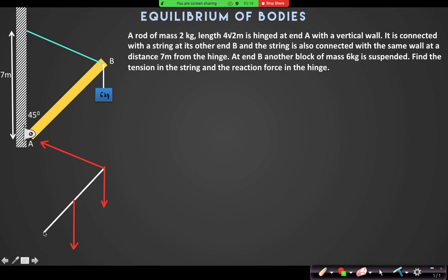And now, what is the hinge reaction? Can you tell me in which direction the hinge reaction is acting? So that I could not find out. Yes, that no one can tell. So always take two components of hinge reaction. One is vertical, another is horizontal. That's the safe choice. You should have said this earlier. So whenever you do not know the direction of any force, you take two components.